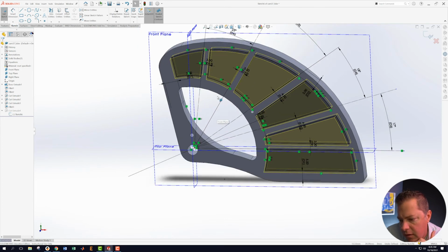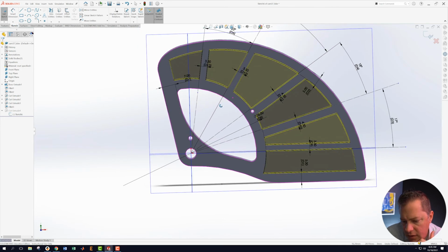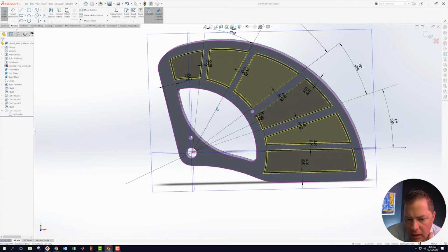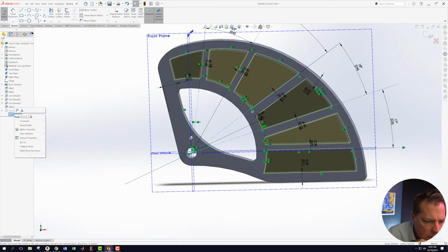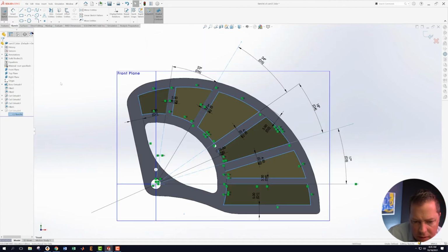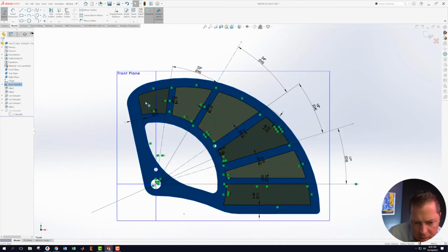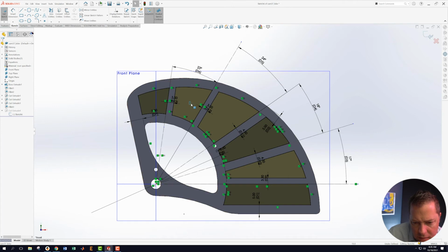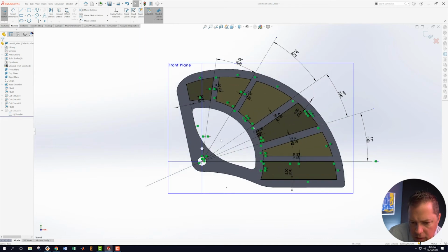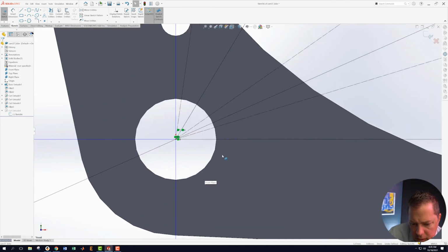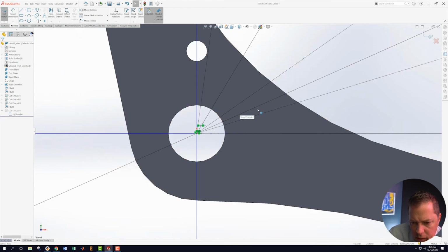Okay, this is part of the problem of sticking so many things in one sketch. Okay, so when we don't know what is underdefined, we can grab things and kind of move them and see what happens. So these are all fixed because they're all black, which means I have another entity floating around here somewhere. Is it way out here? No. Is it down in here somewhere? No.